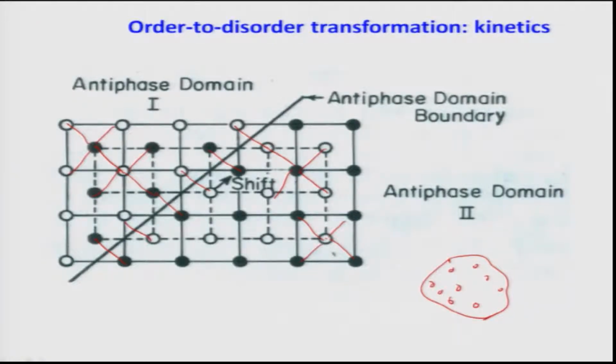You can very easily see this copper-gold atom which is sitting here should have been a copper atom, then the bonding could have been opposite, or this copper atom should have been a gold atom, then this bonding would have been copper. That has not happened. So we can talk about an atomic displacement. Crystallographically, the atomic displacement will be a/2 [1 bar 1 1], and this happens mostly on 110 planes. That can be seen from the crystal structure; 110 planes are why the displacement is happening.